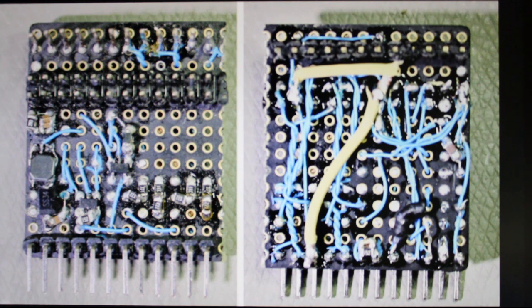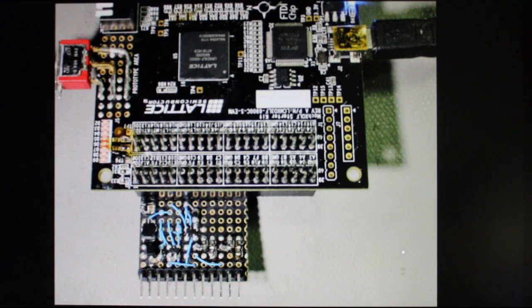On the back you can see one pull-up is on the RST line. The LCD needs a 1.8 volt reset signal. I don't want to engage one more bank for this, so I am pulling it high and using an open collector driver from the 2.5 volt output to generate the 1.8 volt reset signal. Here is how it's connected to the latest FPGA board.